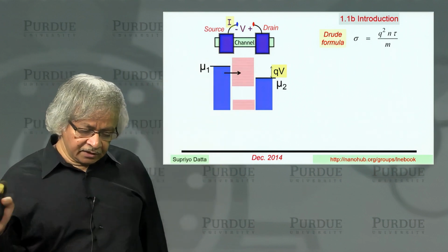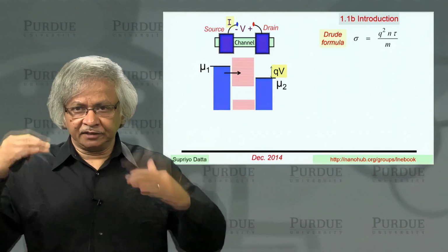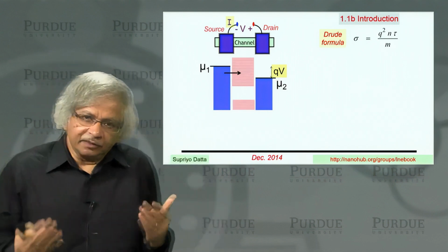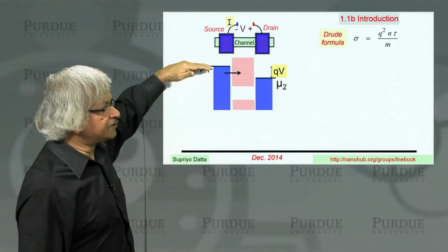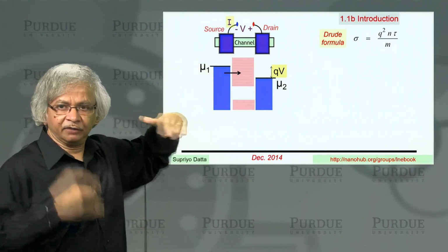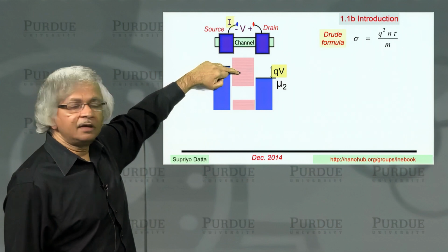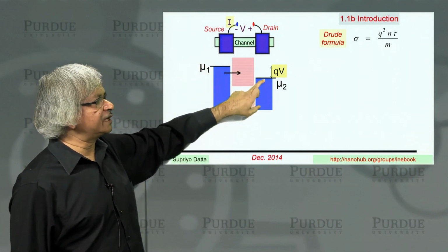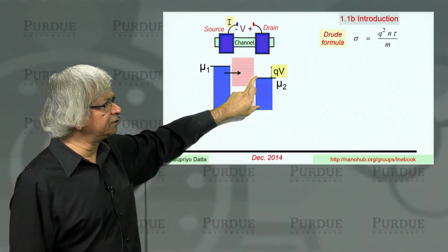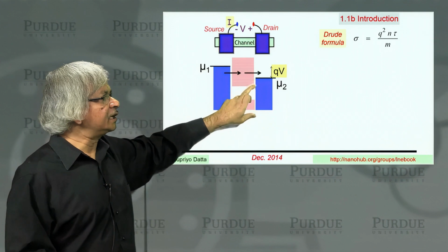In general, just as heat flow is driven by temperature, that is, if temperatures are different, heat flows, similarly with electrons, what drives the flow is this electrochemical potential. If they're equal, then you have equilibrium. So this contact wants to fill them up. On the other hand, this contact has its Fermi level or electrochemical potential down here. So it would like to keep those states empty. And so what it does is it pulls them out.